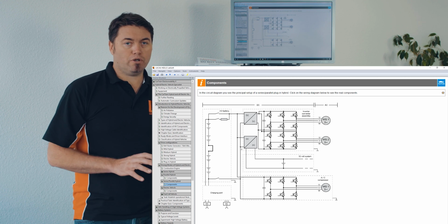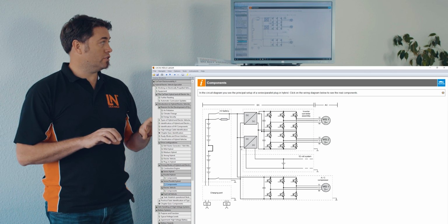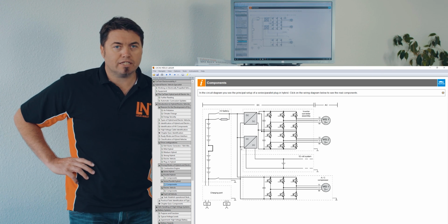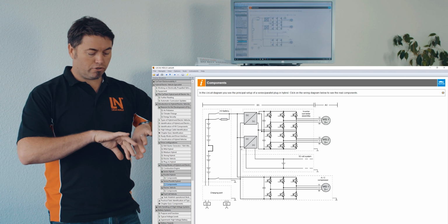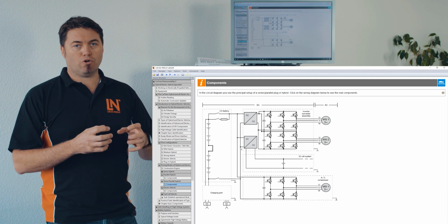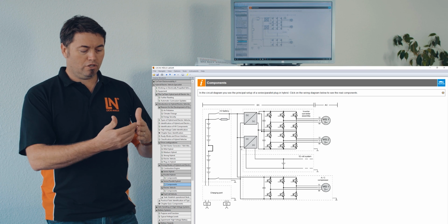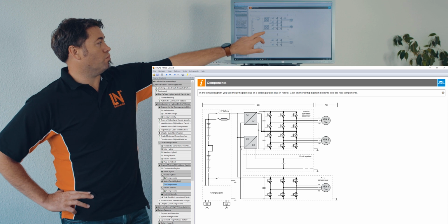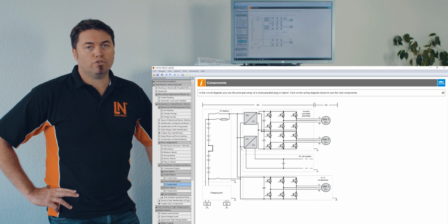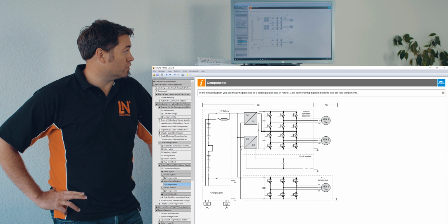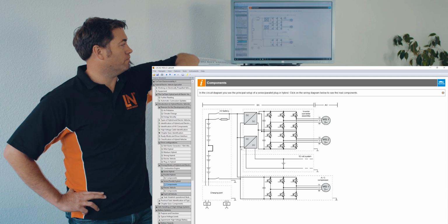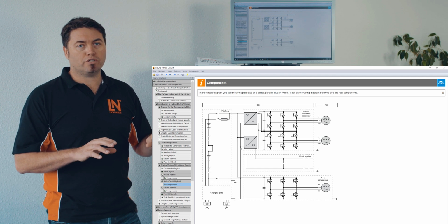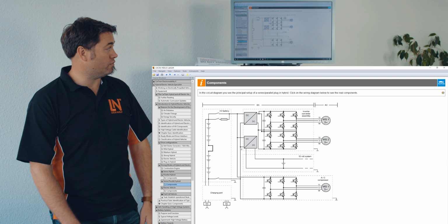Now, it's very important that they're two completely different systems. This one needs to be what's called galvanically isolated. So it's completely isolated. There are no touching parts. It's using a transformer within the system, which is basically wirelessly converting the voltage to your normal 14.6 volts to charge the 12 volt battery. Very important. That way we're also isolating this high voltage system, yet another system for safety within the vehicle.